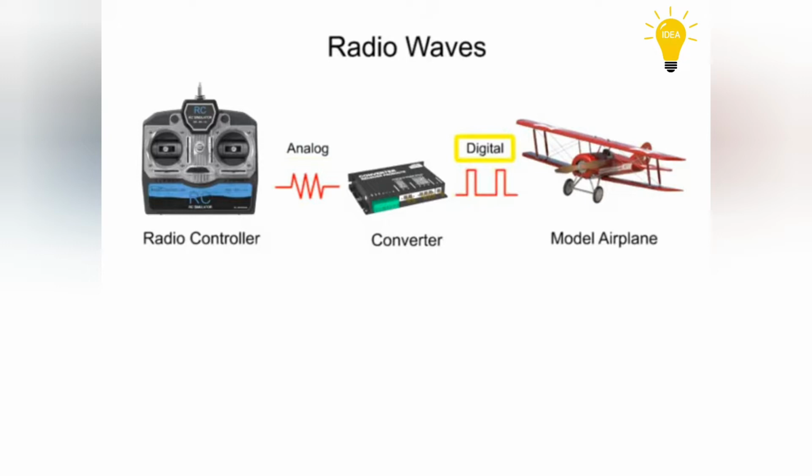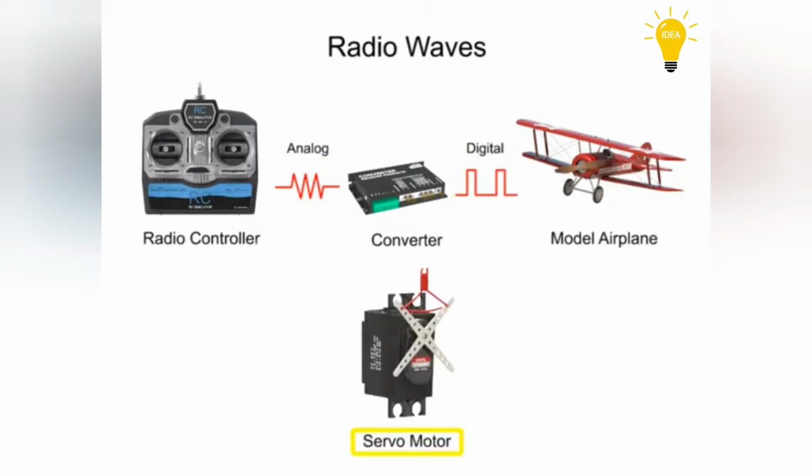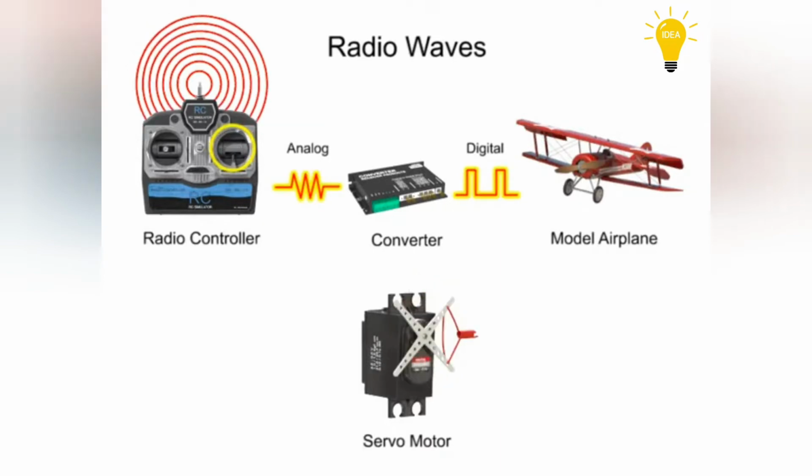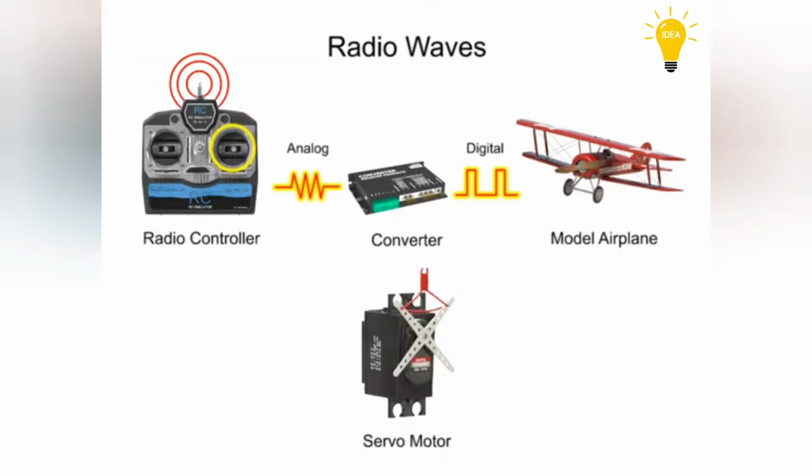These digital pulses are delivered to a servo motor, instructing it to hold a particular throttle or flap position. The width or duration of the pulses will vary based on the position of the joystick. The control pulses only last a few milliseconds and repeat about 50 times per second. A specific series of impulse signals will hold the servo horn in a fixed position.